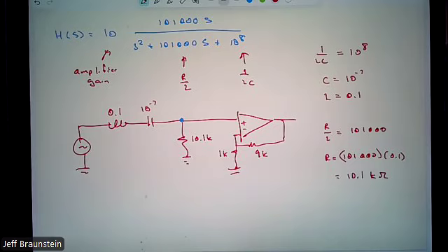So this current is zero, which means the current here is what relative to here? So when I do KCL, if I have current coming here, where does it have to go? It has to go down. So the current here and the current here are the same, which means these are in series. If I put an inverting amplifier here, I have a resistor on this path. And then all of a sudden this and this are not in series. We had drawn that once before, but in general, this is why non-inverting is a better choice in cascaded circuits.